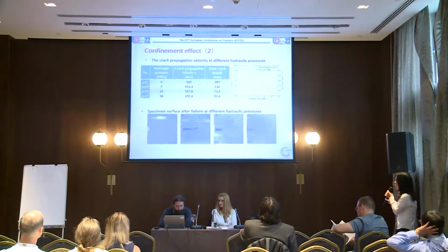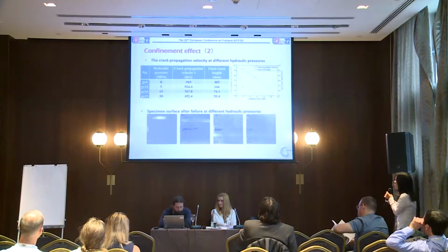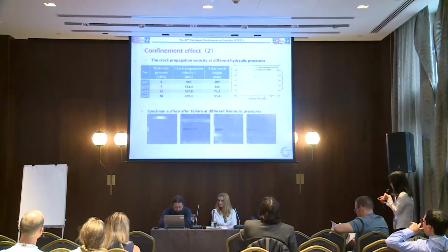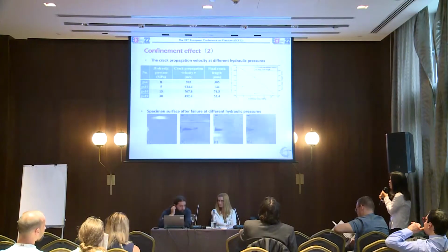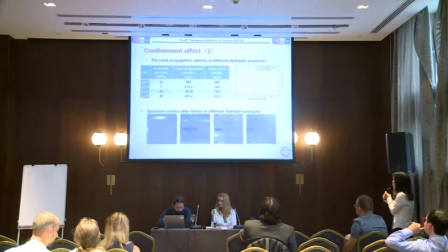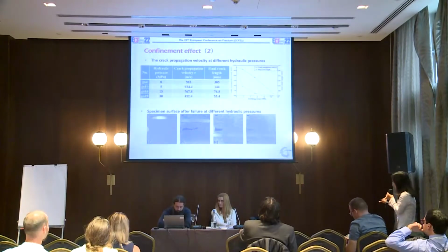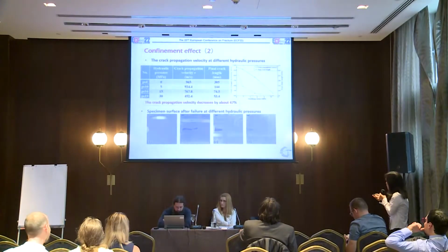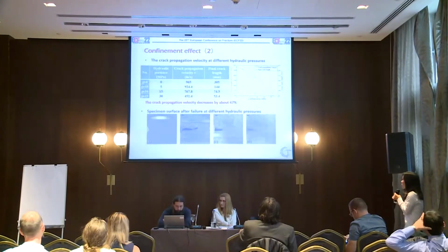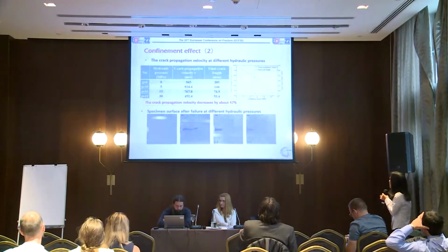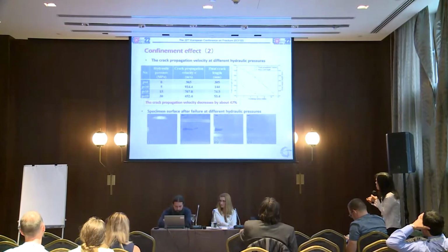Here, for the hydraulic pressure we used, the result is here. The crack propagation velocity at different hydraulic pressures is quite different. It decreased about 47%. And the crack path is also quite different.